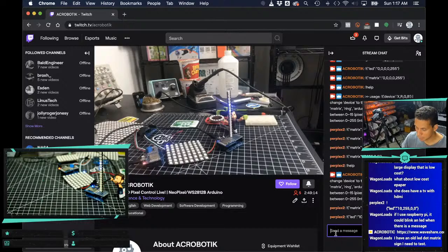All right, uploading is done. Now I'll go in here and tell the matrix. I still need to work on some things, I'm in the middle of making some changes to Twitch. For the matrix, which I don't have in the help message, it takes 2 numbers: the X position and the Y position of the LEDs first, and then the 3 numbers for the color. So 1, 2, 3, 4, 5 numbers instead of 4.